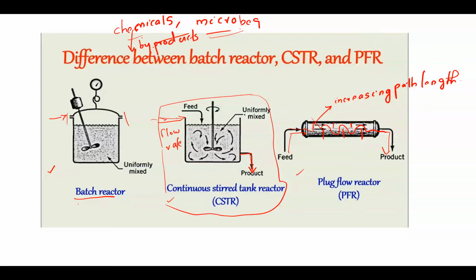So when it comes to handling, the byproducts formed by these chemicals are a huge challenge, because again we have to process the byproducts produced by adding these chemicals. It is a big challenge. So at this time, adding microbes is quite a sustainable way of treating the wastewater in this reactor chamber.